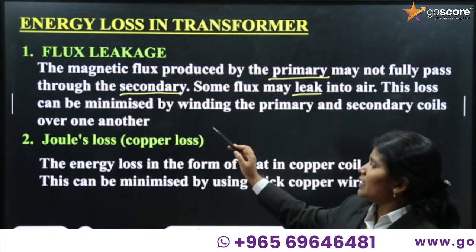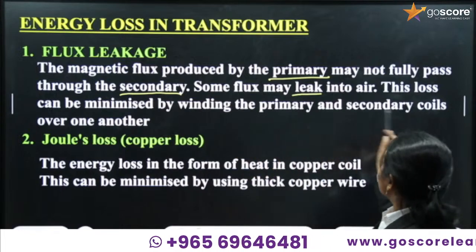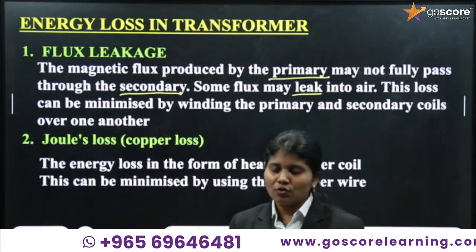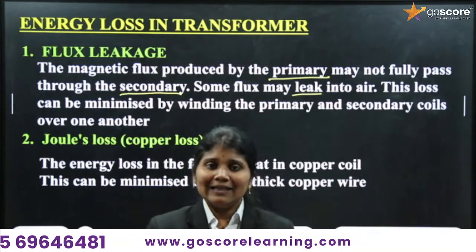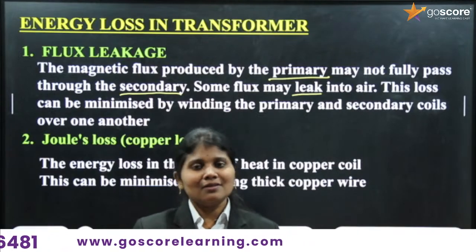This loss can be minimized by winding the primary and secondary coils over one another. We will connect them, then we will reduce this leakage. Otherwise, we will reduce this loss.